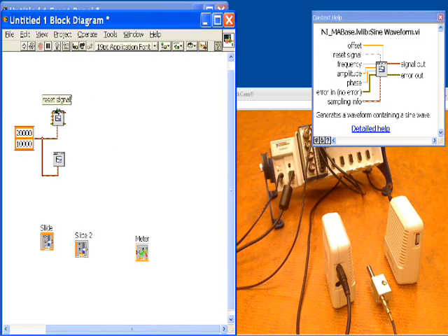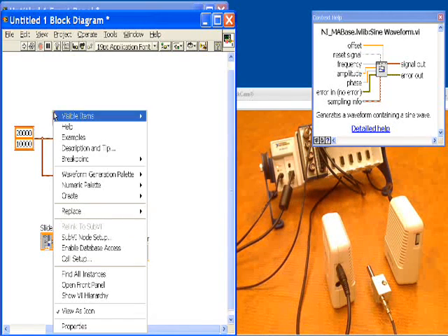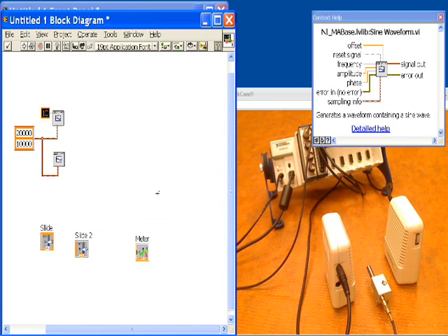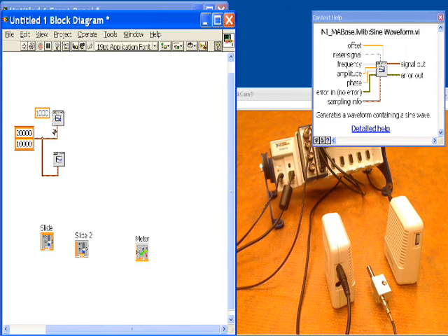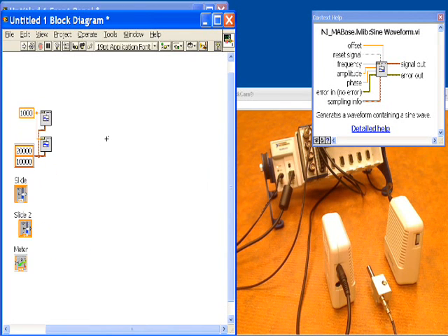The second thing we'd like to do here is set the frequency of the sine wave, and let's generate a 1 kilohertz tone. So we'll put 1000 here, and that'll be a good tone that you can hear audibly from the amplified speakers. We'll share that among both of our sine waves as well.